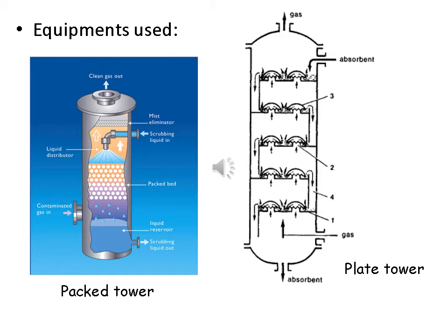The second method, the tray or plate tower, is a vertical tower containing a number of trays. It is often used to contact the hot gas with cooling liquid. Water is the most commonly used liquid for cooling. The working principle: a liquid enters the tower at the top and flows downward by gravity. On the way, it flows across each tray through the downcomer to the tray below.